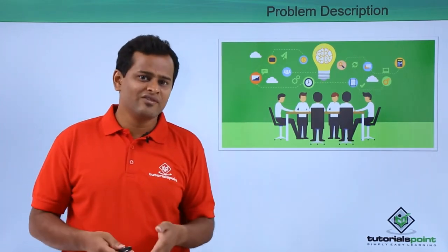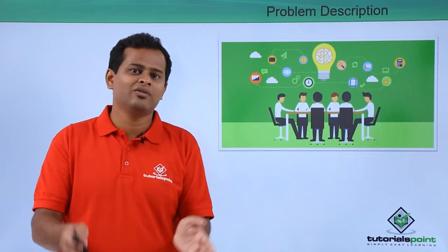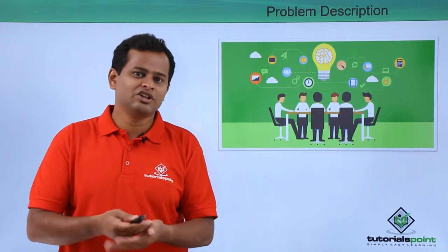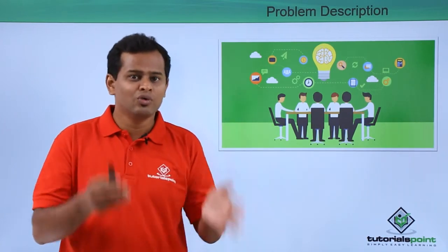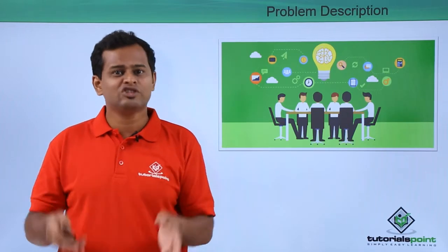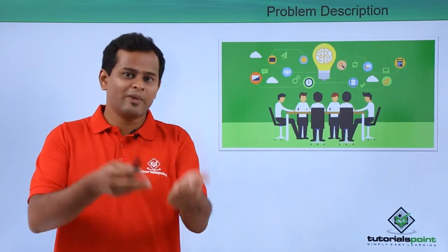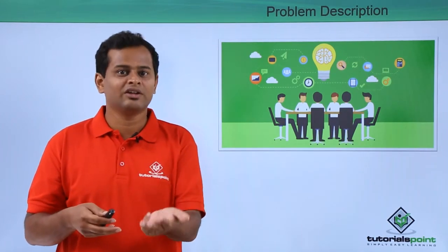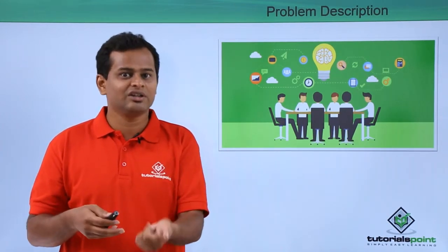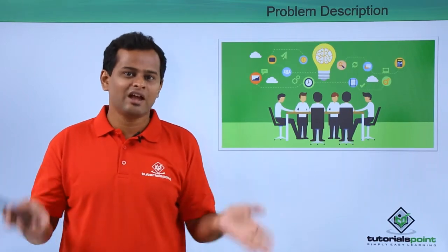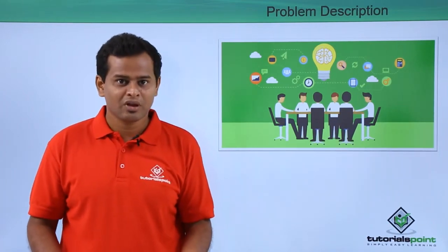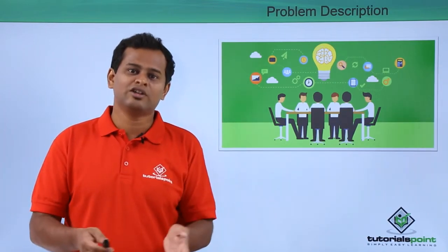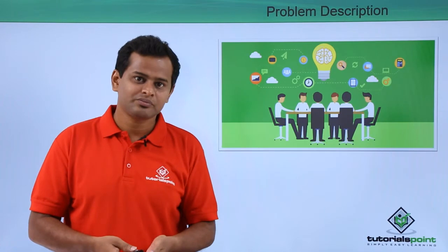So before we have a problem description, we need to have a problem solving team. And in this problem solving team, there should be all the representatives who are responding for this particular problem, like from manufacturing, from logistics, from supply chain management, material planning, from quality, supplier quality, purchasing, like that there can be various departments. And then we need to describe the problem very clearly by 5W and 1H principle.